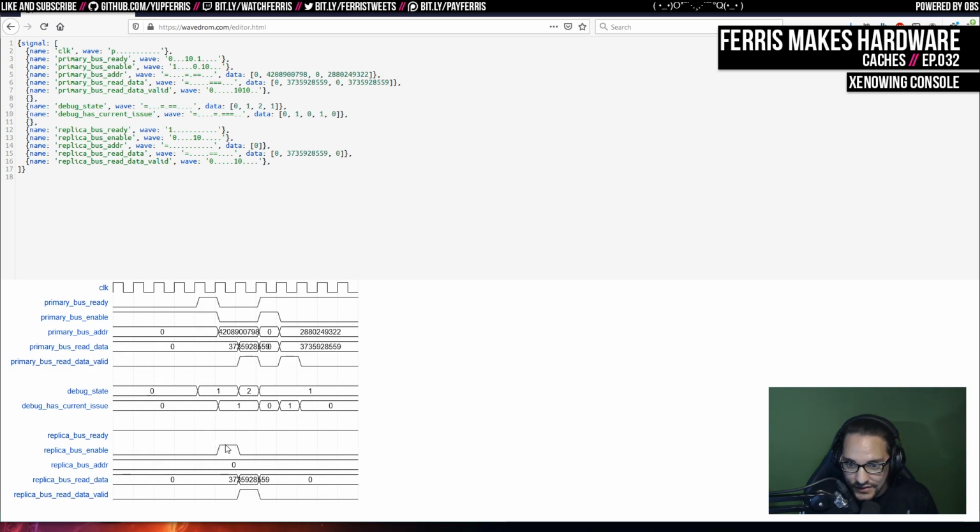it wasn't in the cache. So on the cycle following it, it immediately issues that read to the underlying thing. And in this test harness, just to make things simple, I only return the read on the following cycle. I might spread that out just for testing purposes, but I think I'm going to do a big fuzz test with this thing to make sure it is correct, because I really want to be able to trust this.